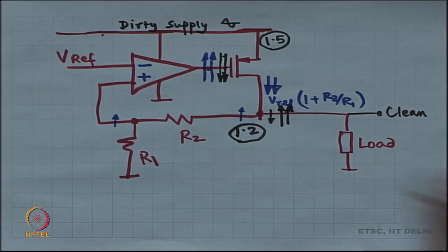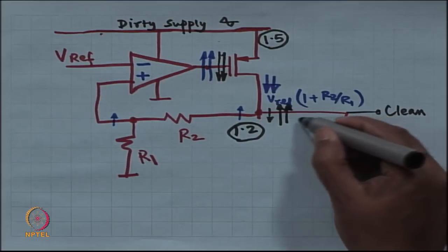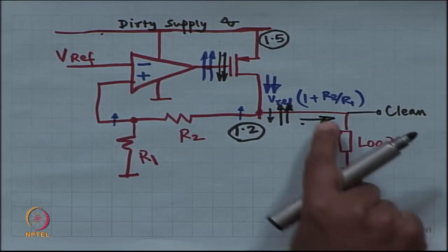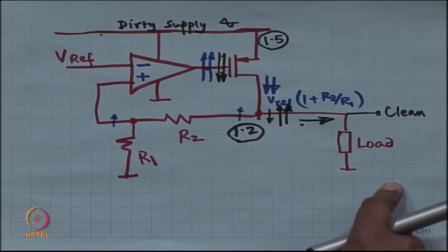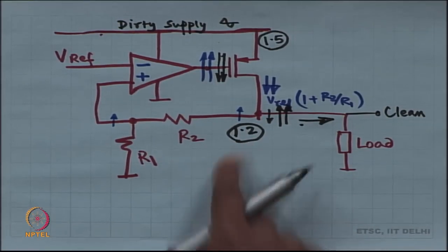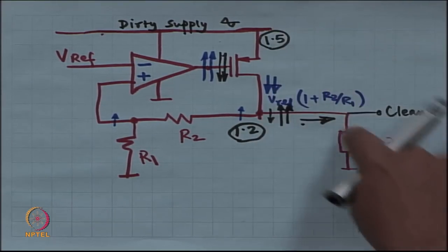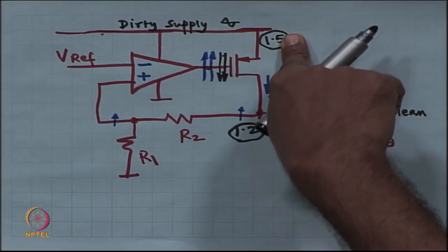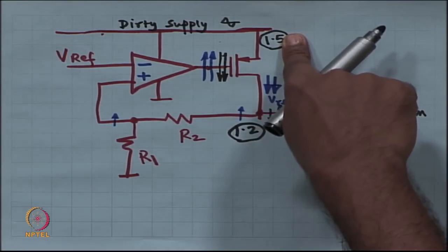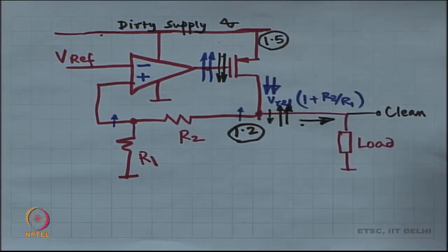all right. So, let us do the same thing. I draw 50 milliamperes over here, right, power delivered to the load is 50 milliamperes times 1.2. So, that is 60 milliwatt. Power drawn from the source is 50 milliamperes times 1.5, right. Overall efficiency is 1.2 by 1.5, that gets you 80%, a lot better than what we had. 80% means you are now closing in on very high efficiency.